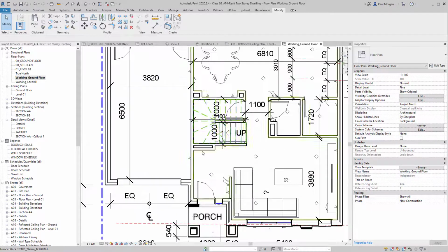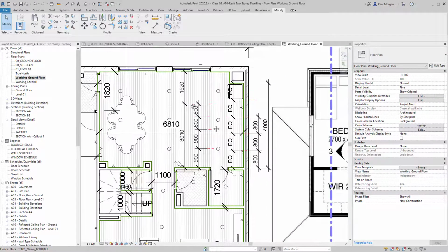There are two ways that we're going to model joinery families inside our assessment task. The first method is the more simplistic method, which is to model families in place inside the model. And the next version is a more detailed methodology where we build a joinery family in an external environment using nested families and then bring that whole module into the project as one superfamily essentially.